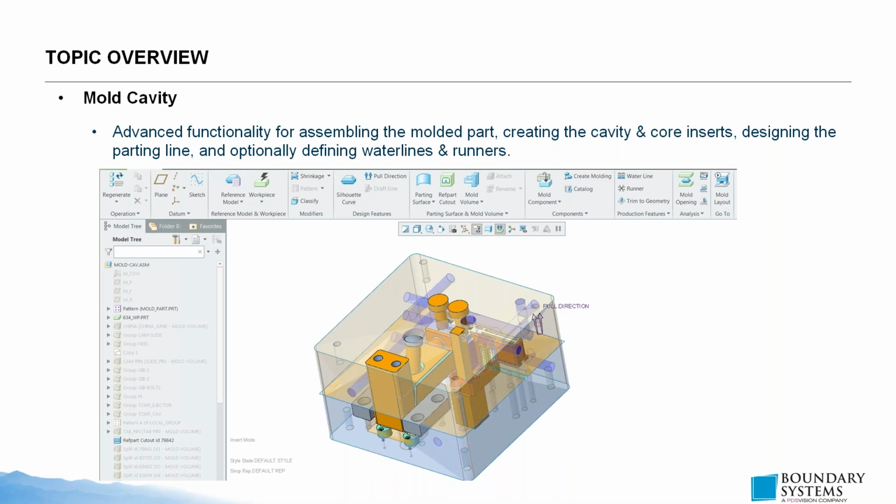And mold layout has extensive functionality for arraying and positioning, rotating as necessary, these cavity insert sets that are created in the mold cavity functionality itself. And that is the base workflow, that is, adjoining the cavity set to the mold layout. And hopefully that brings more context to the concept of mold layout.